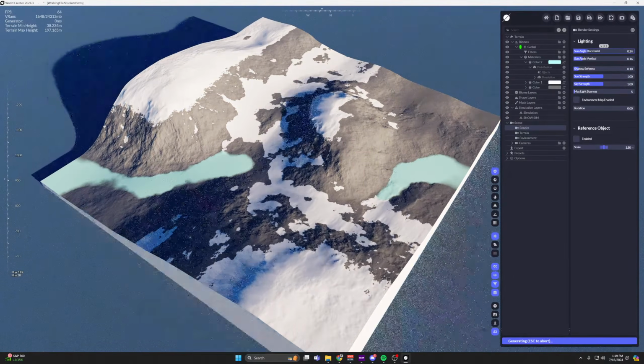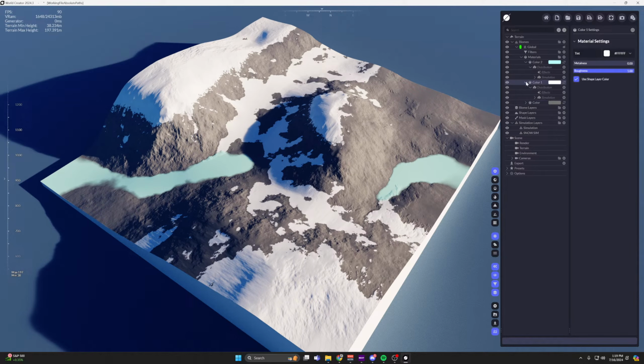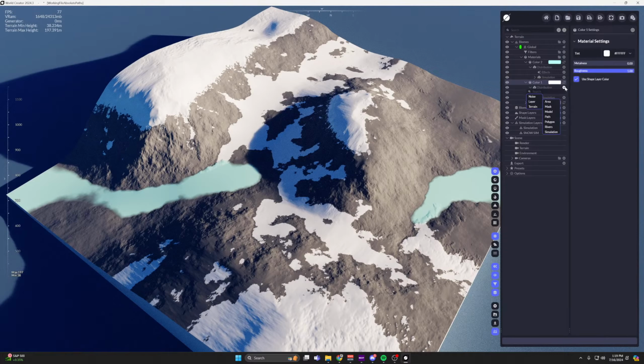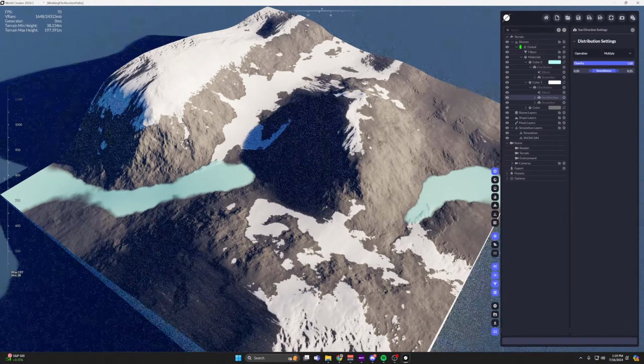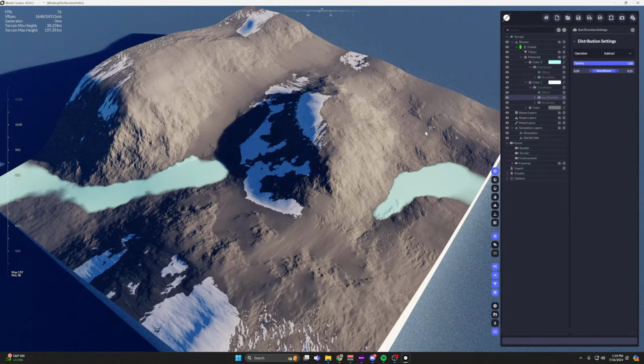areas, not the vertical. So one thing that you can do, for the snow color here, if you want a little bit more of that snow to be removed from the sun angle, under distribution, terrain, you can add sun direction. And then for this, you can add subtract.